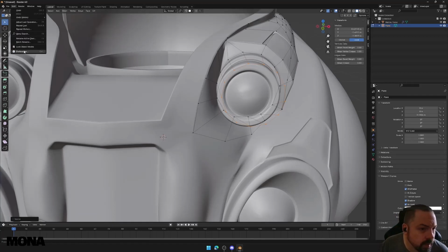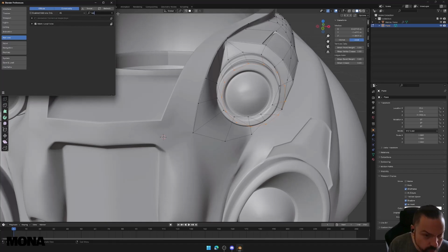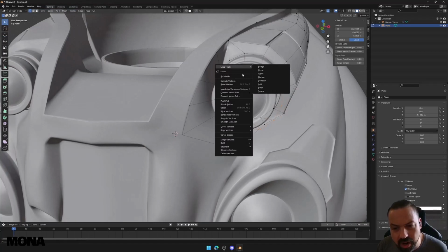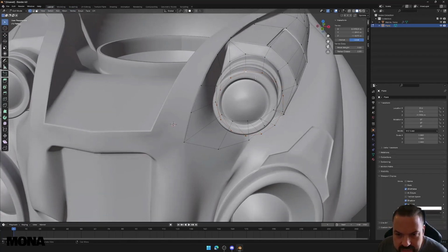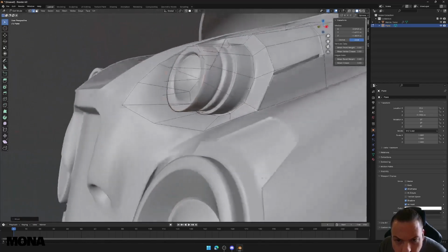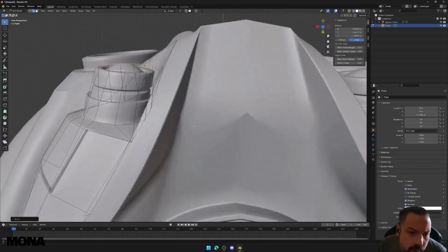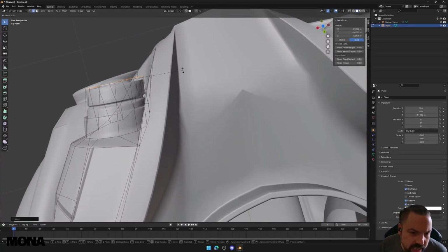But the add-on, once again, preferences, click that one, and type in Loop Tools and make sure that is on. Because Loop Tools, and there are other ones, but I pretty much always use circle. So as an example, let's see if we can line this up just a little bit better. Now note that you will rotate according pretty much to your screen.